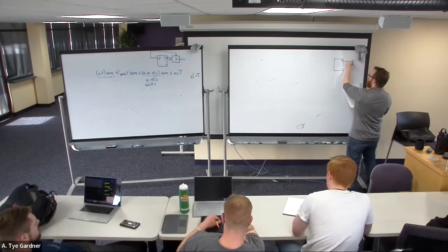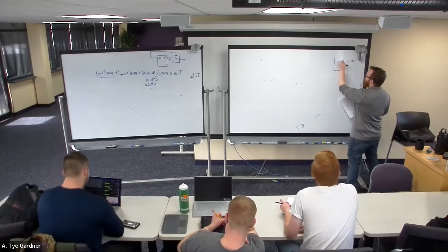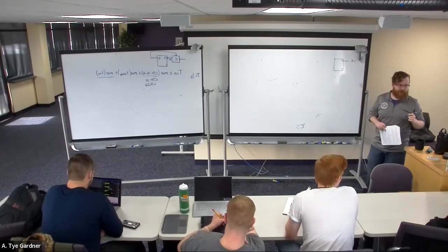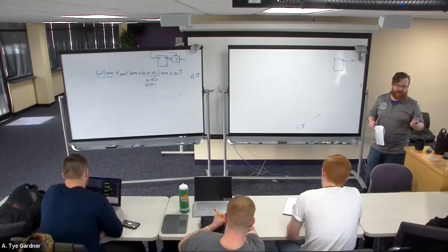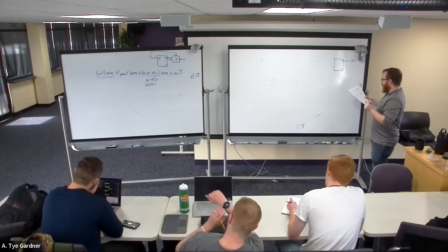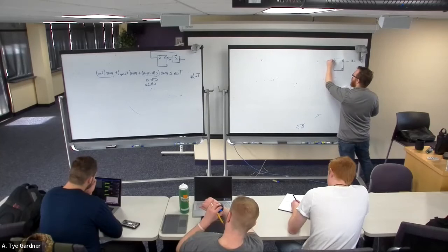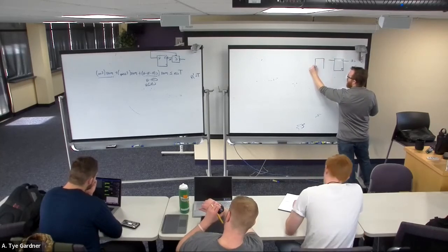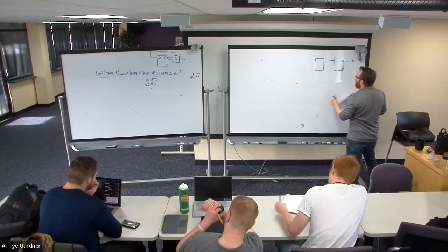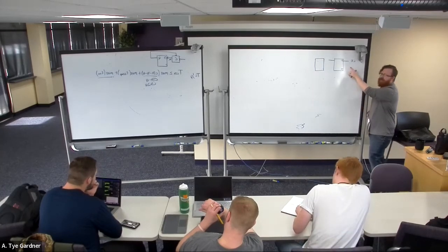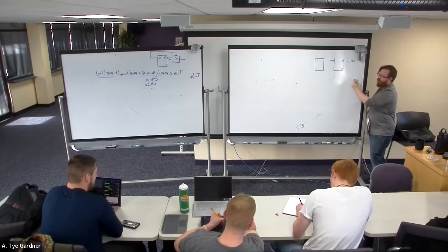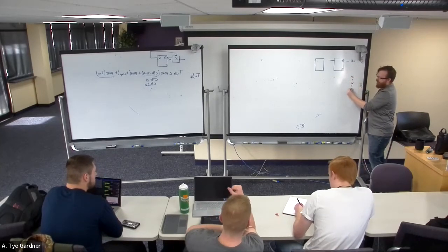And we're going to call the input to my first flip-flop CE for clock enabled. Is my clock running or not, right? Am I counting? And then I'm obviously going to need another one. In fact, what's funny is this T flip-flop, if the clock enable is 1, every rising edge of a clock, it's going to go 0, 1, 0, 1, 0, 1.